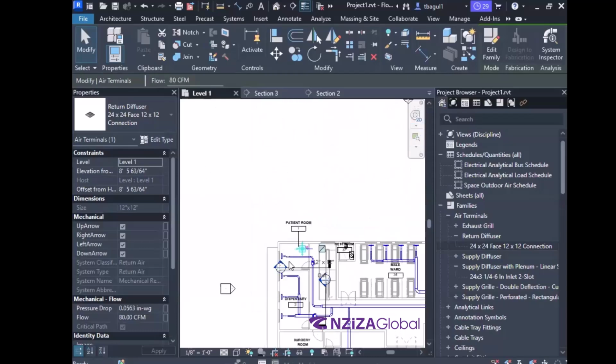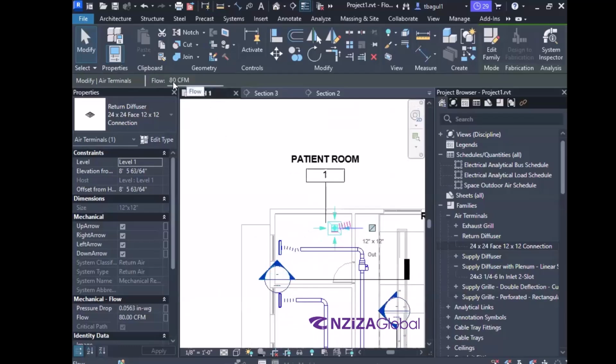So now over here, we are still going to put 70 CFM because we want the room to be positively pressurized to make sure the infiltration load is not overpowering the internal loads. Okay, we need the extra 10 CFM to seep out.